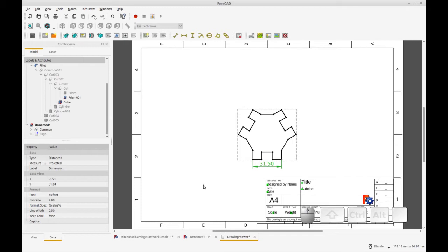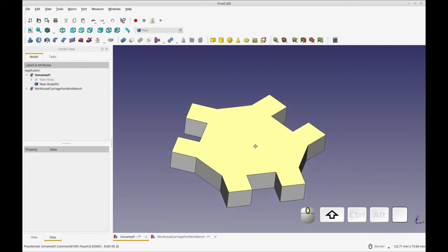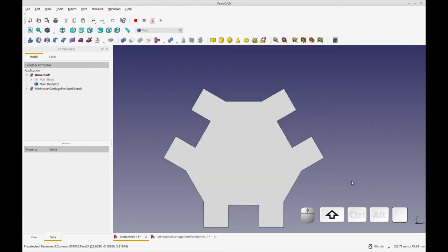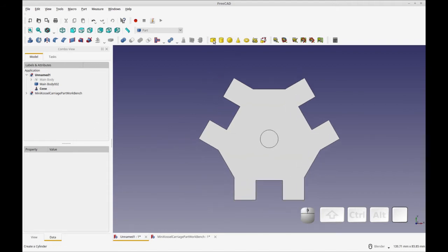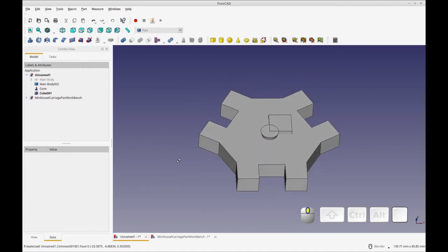I don't know. The next bit I want to add is the standoff for the rod ends. And each plane will have one standoff. So let's start by orienting this from the overhead view. So we're going to want to orient the cone. It's a cone-shaped standoff. It's going to be oriented on this axis and plane here. So we're going to add a cone and a cube because we're going to combine those two to make our shape.